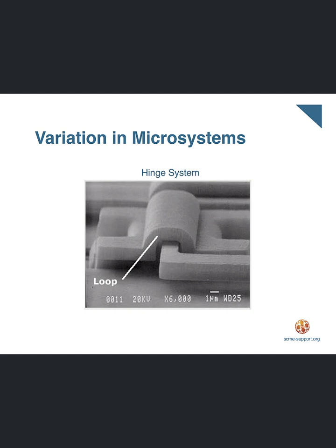Microsystems deal in micrometers and nanometers, not centimeters and inches. Because of the extremely small feature sizes, 1 micrometer to 100 micrometers, and precise alignment, sometimes in the nano range, microsystems fabrication needs to be on target, from step to step, over hundreds of steps. Remember the example of the micro-pressure sensor process? There are so many steps involved in microsystems fabrication that when variation occurs at one step, it can perpetuate and affect other steps along the way.